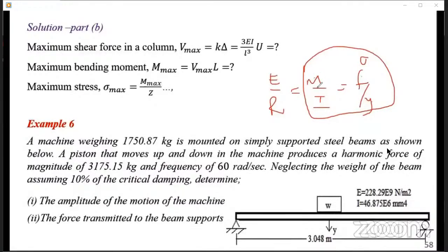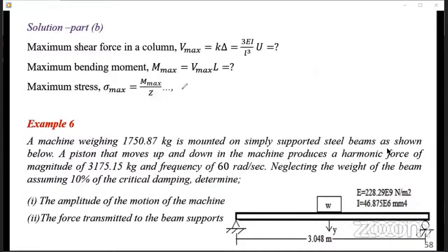This is the second moment of inertia. So if you don't have this Y, that's why you need to know how to relate the section modulus. The section modulus is equal to I over Y, right? I hope you recall that. So you need to get the moment.